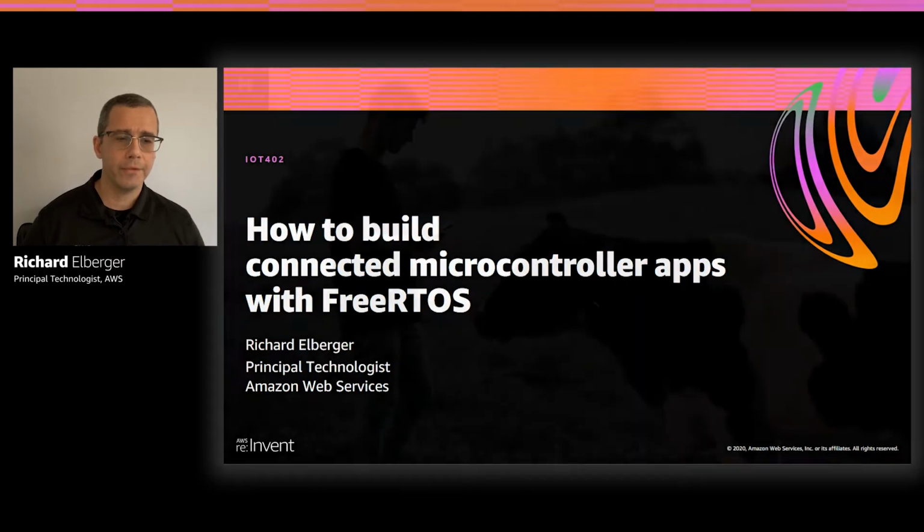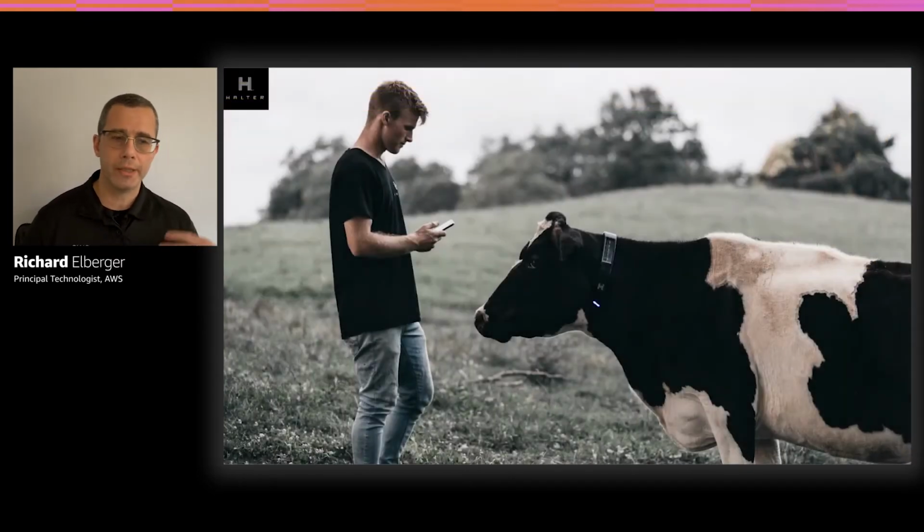So I'm going to start with this wonderful story from New Zealand. It perfectly demonstrates the complexity that IoT faces when connecting to the cloud from the wild. It surfaces multiple challenging factors: device power, radio range, and throughput. We're not going to run extension cables to cows, right? So these cow-connected devices need to run on battery too. They need to be efficient. When the cow is kilometers away in a pasture, the device won't connect to a centralized Wi-Fi router at that distance, right? So we need to think about low power, wide area networks, radios like LoRa or Cat-M.